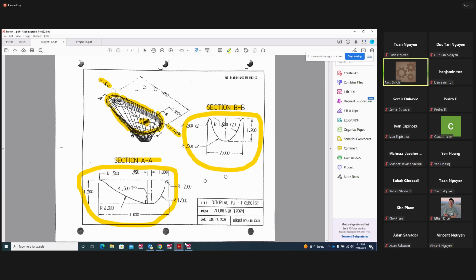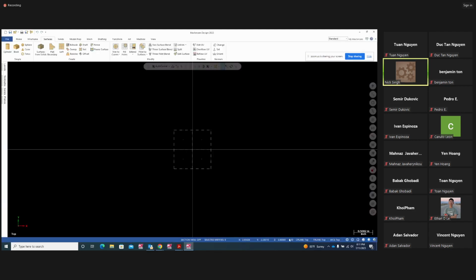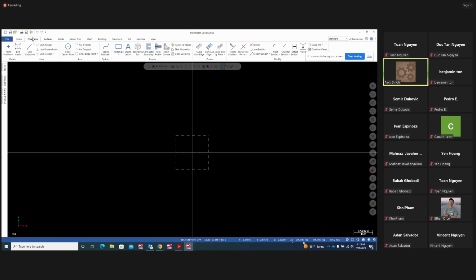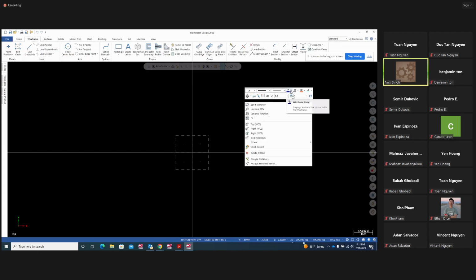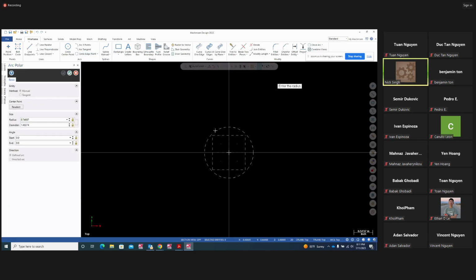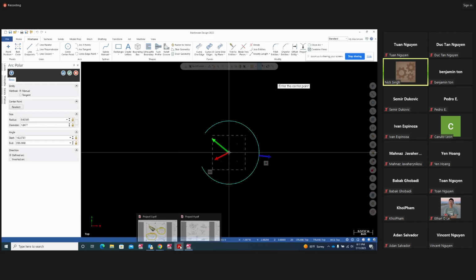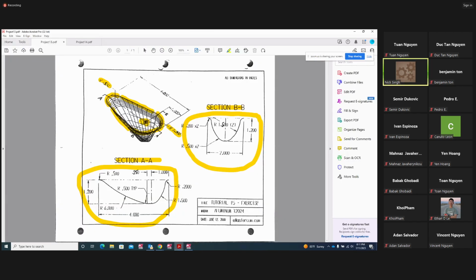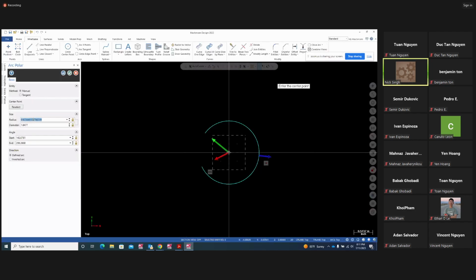So let's go to here. We are in 2D. Construction plane is top. And we're going to start wireframe. Let me change my color here. We're going to go color green. So wireframe arc polar. And that arc with that center point, I'm going to start arc from there to here. And that radius of that arc is 1 inch right here. So put the radius 1 inch.